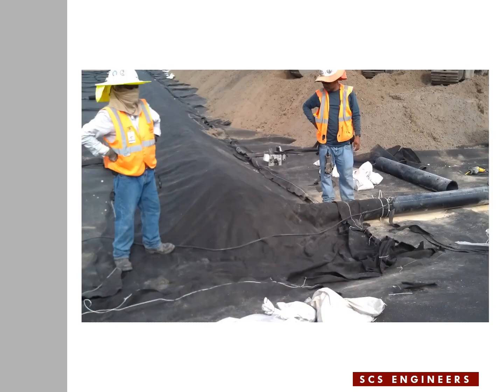In this slide it shows the termination of the LCS pipe, as I explained in the previous slide, embedded in gravel, geotextile is pulled over it, and to the right side you see the solid pipe which brings vacuum to the gravel bedding around the LCS pipe. Since the solid pipe is penetrating the geotextile, a geotextile boot is installed over the solid pipe and the plastic ties are visible. The boot and the sealing of the geotextile prevents sand particles that are going to be pushed over the geocomposite drainage layer from passing through the textile and then clogging the gravel below it.